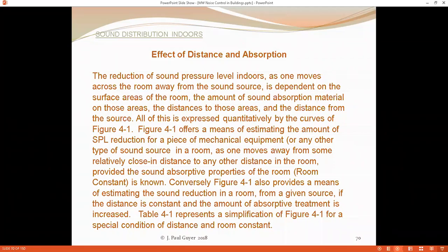And similarly, on the receiving room side, you also have some degree of absorption due to the distance effect between the barrier wall and the human ear. And then there is also a certain amount of that acoustic energy that is absorbed in the receiving room as a result of absorption with finished materials, carpet on the floor, things like that.